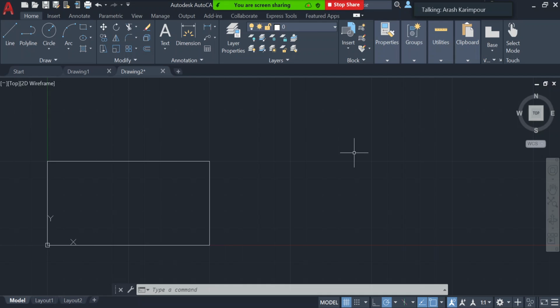One way of doing that is to calculate everything from the origin and then start drawing from the origin. But the easier way, if I have everything relative to this corner, is instead of calculating all the dimensions or angles with respect to the origin, just bring the origin temporarily to this position, draw everything with respect to that, and then bring the coordinate back to its original origin.